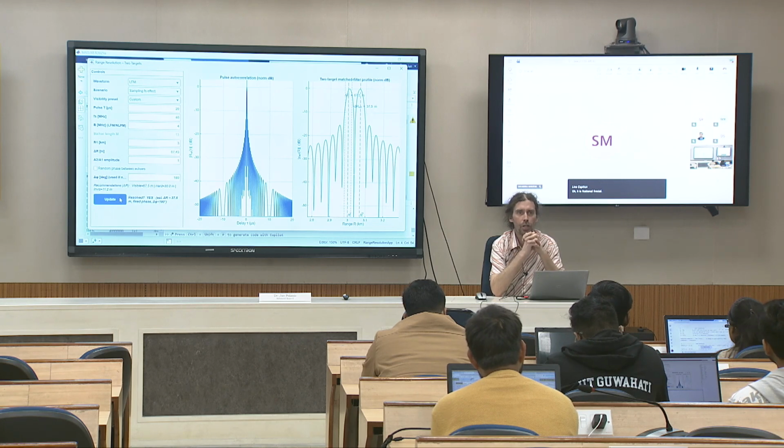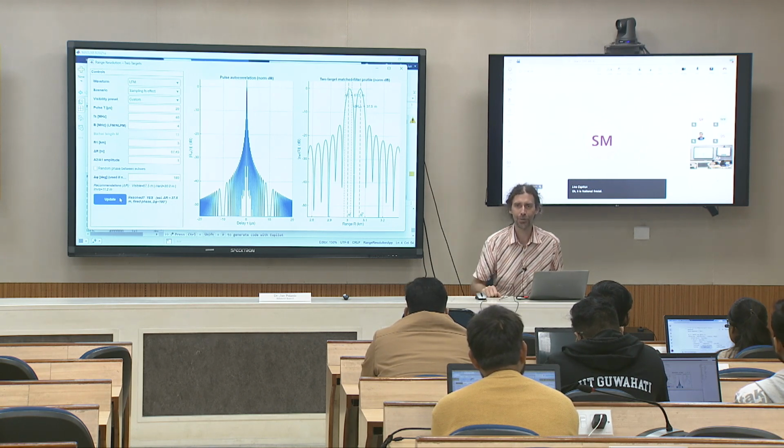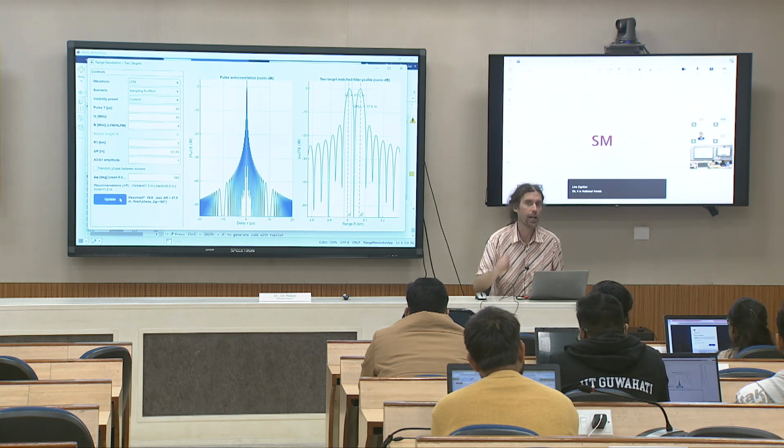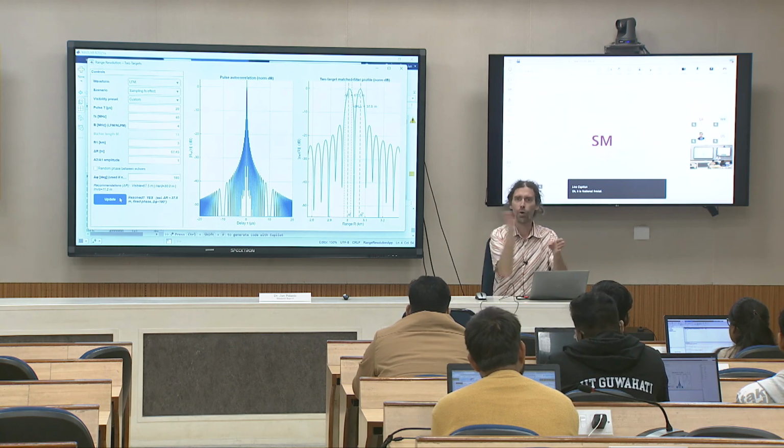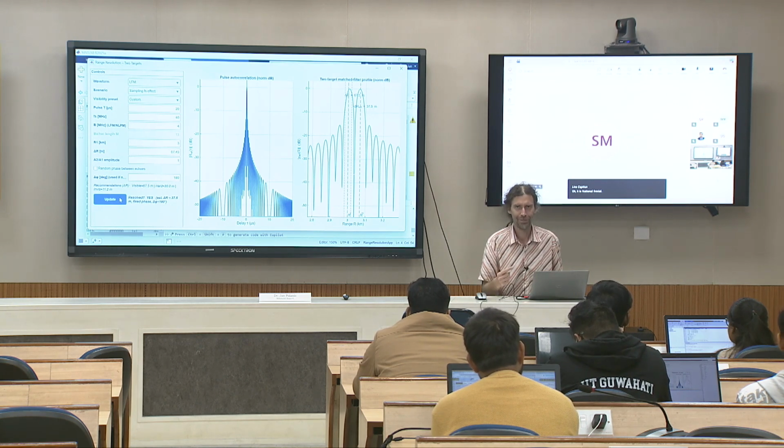I get your answer now. But you are in the commercial zone, and you know why? It is just about money, because it is about AD conversion. And military systems almost always need to work in real time. Yes, the lowest sampling rate. Because if it is higher, you can't process in real time, or your AD converter will be so expensive that nobody buys it. Okay, you didn't tell me the first time that it is commercial, so it is clear, it is just about money, and stability, and the important thing is that it's in real time.